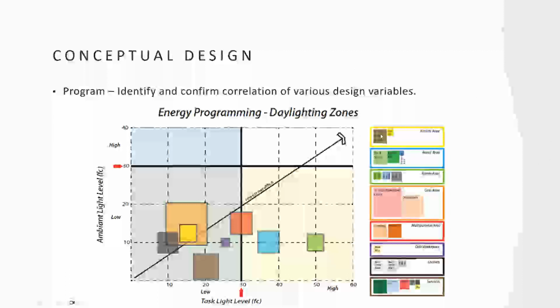So it combines our individual spaces with their thermal zones, and then we're mapping on, okay, here's what IES, the Illuminating Engineering Society, or our manufacturer, says we need for our space: 20-foot candles, 30-foot candles, 40-foot candles. Based off of our simulations, here's the amount of foot candles available currently with our design. So now we can see how difficult it is, how much we have to invest in daylighting to get our levels up to performance, so we can get credit for them and receive a good rate of return for our payback.